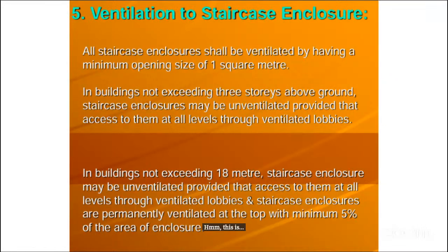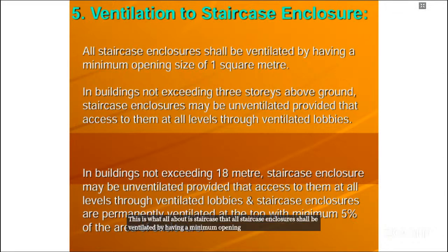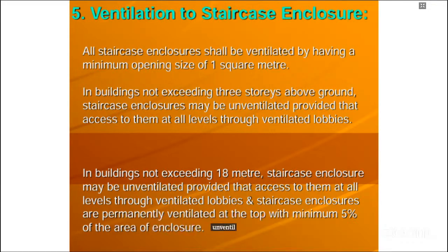This is all about staircases: all staircase enclosures shall be ventilated by having a minimum opening size of 1 square meter. In buildings not exceeding 3 stories above ground, staircase enclosures may be unventilated, provided that access to them at all levels is through ventilated lobbies.